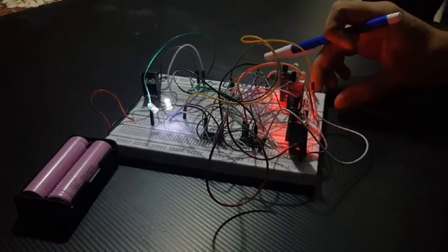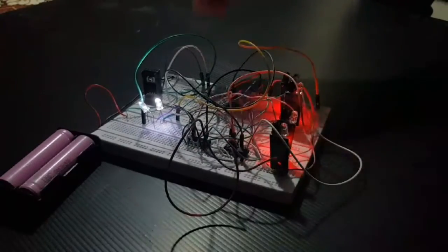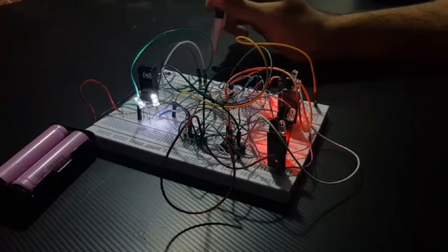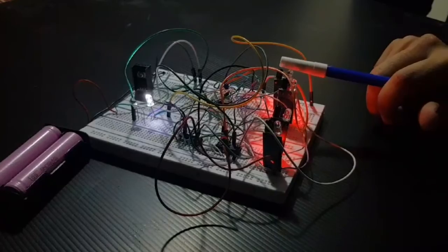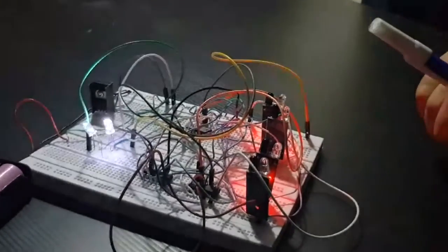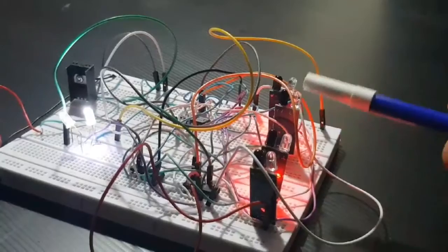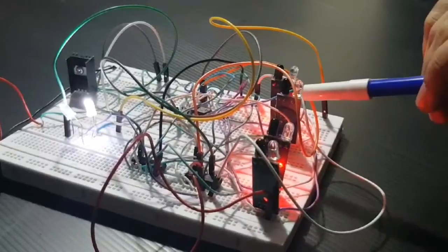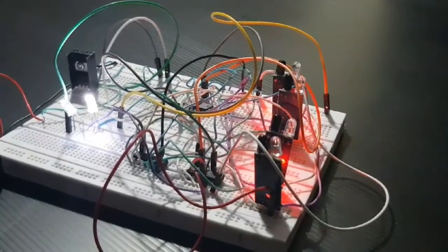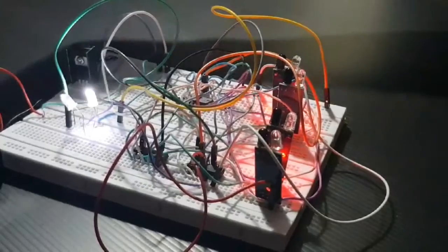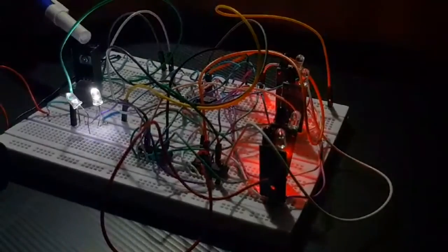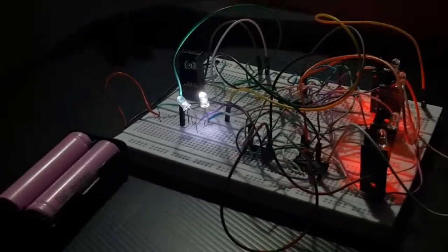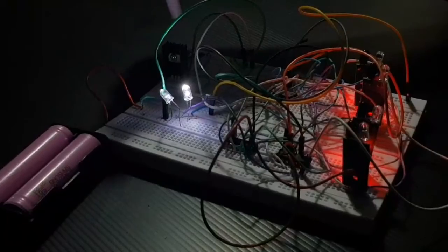So here we have a line follower robot circuit. First of all, we will see which sensor is which one. This is the rightmost sensor, right sensor, left sensor. These both are the center sensors, so we'll name them center 1 and center 2 sensor. Now this is the main voltage regulator, which will convert this 9 volt or 7.5 volt or something like that to 5 volt.